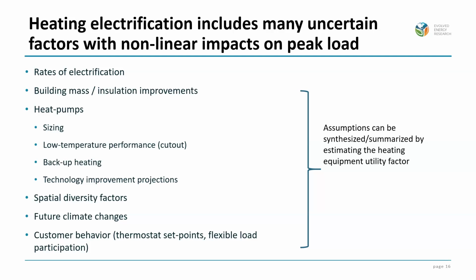So, as the temperature drops, not only does the coefficient of performance on heat pumps go down, but the BTUs of sensible heat also drops, and that's in contrast to, say, a natural gas furnace, where if you're producing 70,000 BTUs out of a natural gas furnace, it doesn't matter if the temperature is 0 degrees or 50 degrees, you're still going to have the same capacity, and that's different with a heat pump.